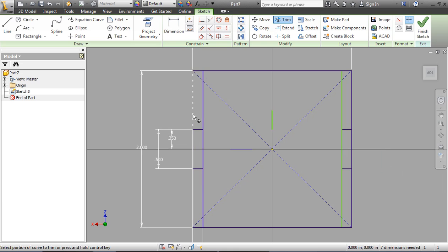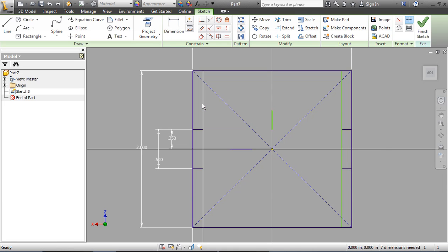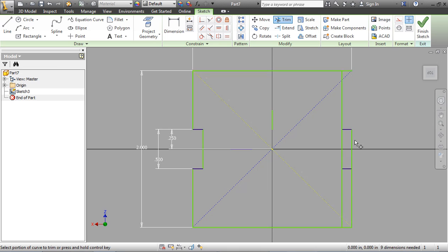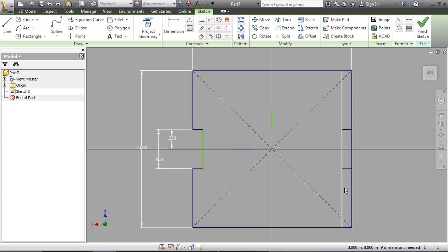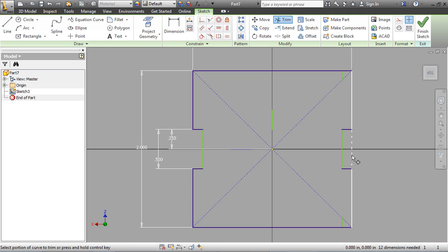So I'm going to click on trim, and I know for this side I don't need this line. That's a lie. Control Z it to get it back. That's right. We don't need this line here. So go to trim and trim this. Trim this little bit out and that bit out there, and we're going to trim this out there. And then once again on this side I can trim these parts out. Control Z, grab the wrong one. Trim this line here, this line here, and that line there. And you can see that I have now my two sides or the indents or the tabs.